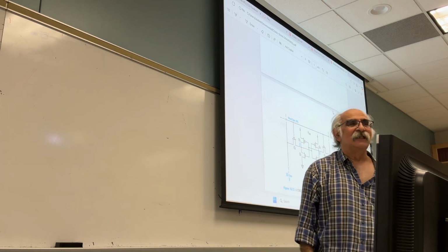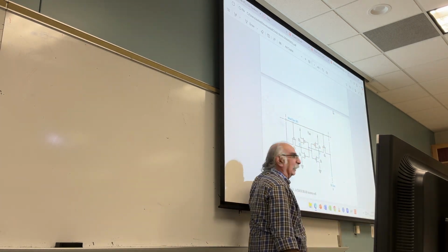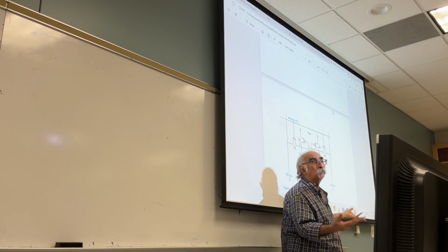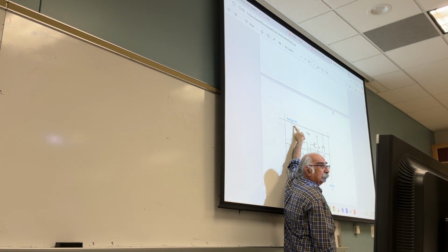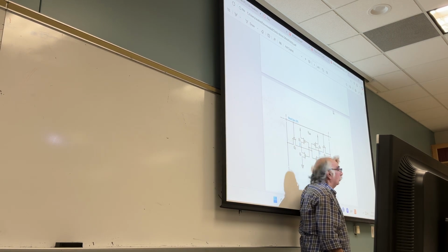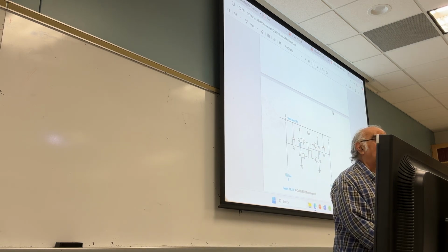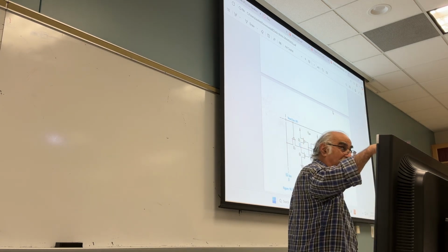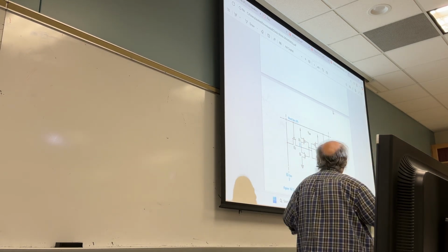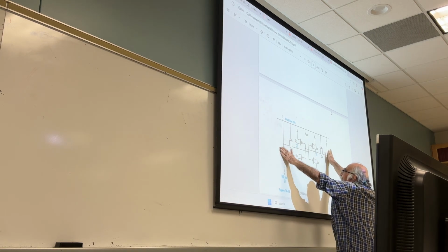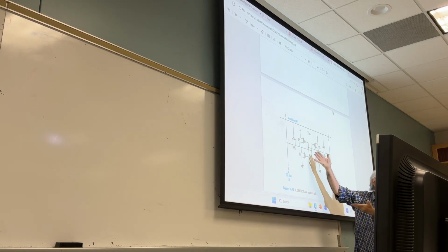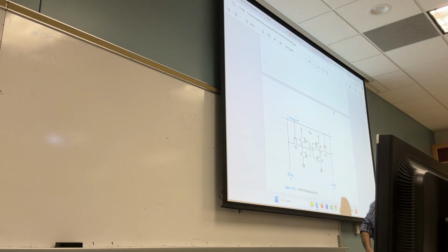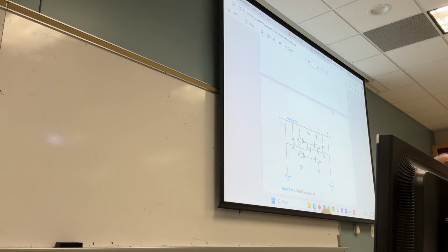Good. Now, let's understand the thing here, first of all. This is a pass transistor logic. It's an NMOS. So when you have a 1, that NMOS will be on. Did you get it so far? Yes. If it is off, in other words, if the word line is 0, what do I have? I don't have this, and what do I have? Back-to-back inverters, which is a latch. Did you get it or not? Yes. Which means there is no change in the state.